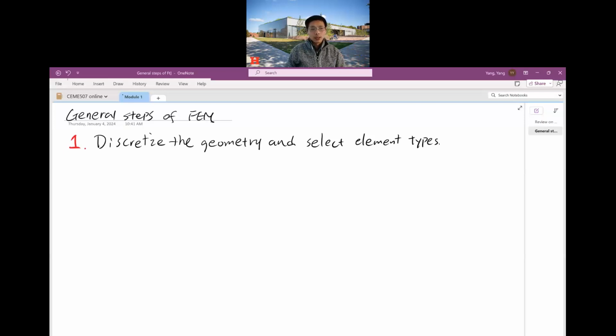You need to use some strategy to divide the geometry into smaller regions or smaller shapes, such as rectangular, quadrilateral, or triangular smaller shapes there. So that in the smaller shapes, we can use the approximation of any method to find the relationship between forces and the displacement here.